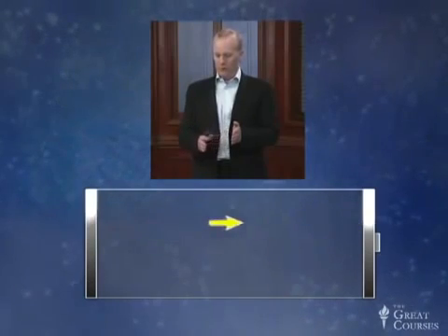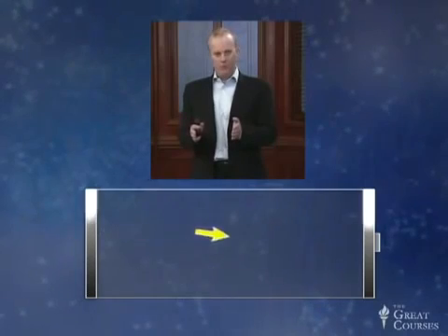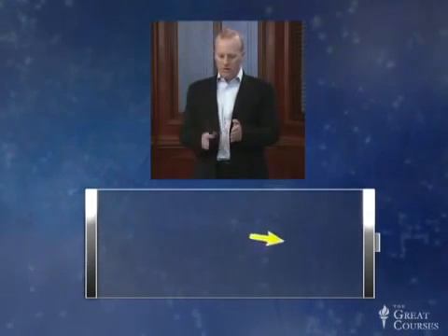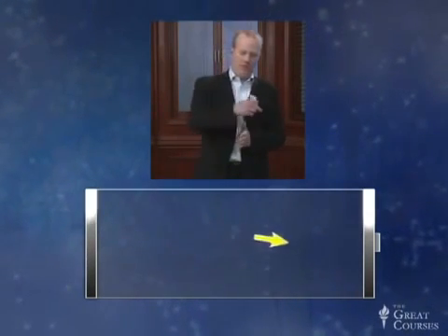The second ingredient is a resonance. You can also think of this as feedback. In the simplest terms, the front and the back of a laser are both mirrors. They're not perfect mirrors. If they were perfect mirrors, then light generated between those two mirrors would always remain trapped. But if they're just slightly less than perfect mirrors, light is mostly trapped, and then occasionally it can escape out the front facet. It can be transmitted through the front mirror that has a less than unity reflectance.